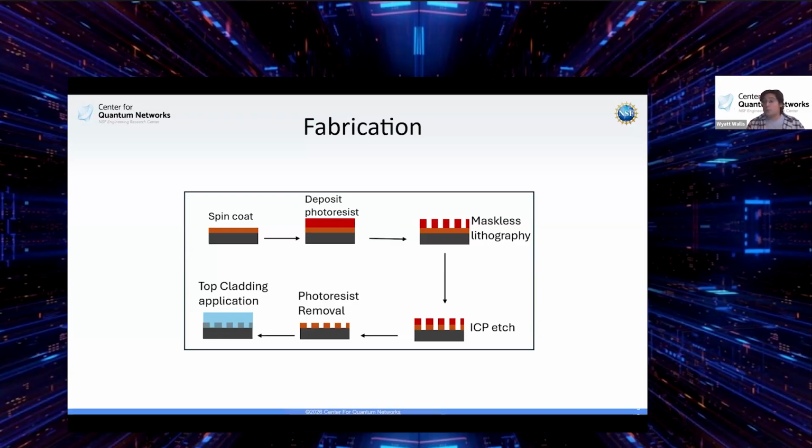And depending on what type of photoresist you have, you would then take it out of the machine and develop it in a different compound. And when it develops, it either takes off the stuff that was reacted with, or the stuff that didn't react with the UV light. And then that leaves your pattern. All right. Then after that, you run it through an etching process, and we'll talk more about that. And then that gets rid of all that orange that's underneath that's exposed.